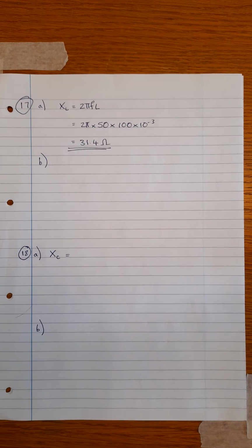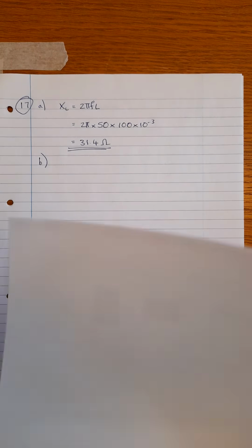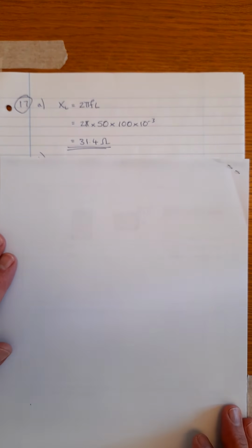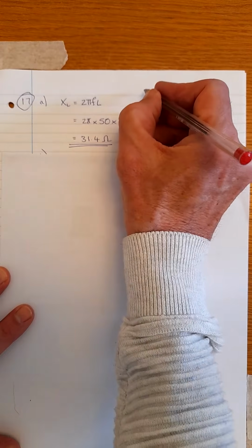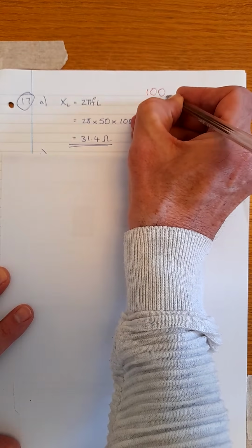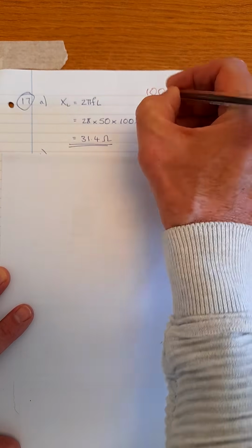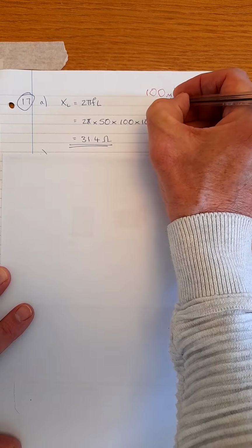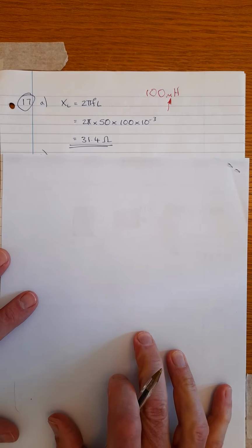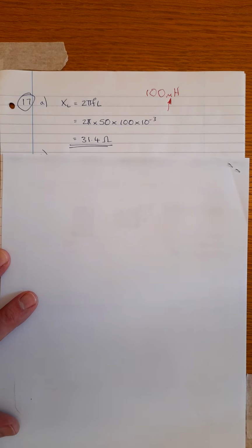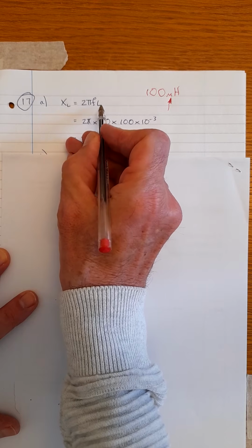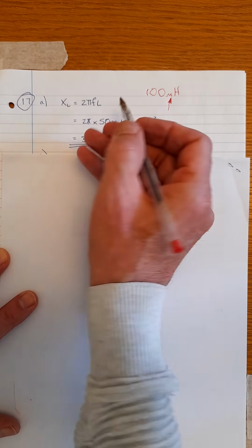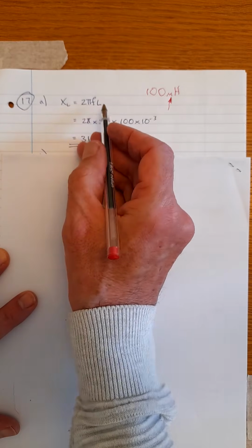16, and let's have a look at question 17. I'm very conscious of the time. Right, so question 17. This is about a 100 millihenry inductor. 100 millihenry. You cannot ignore that in anything you do. So first part was to find the reactance. XL equals 2 pi FL. We'll talk about the marking of this in a moment. So there's your formula. Put the numbers in.